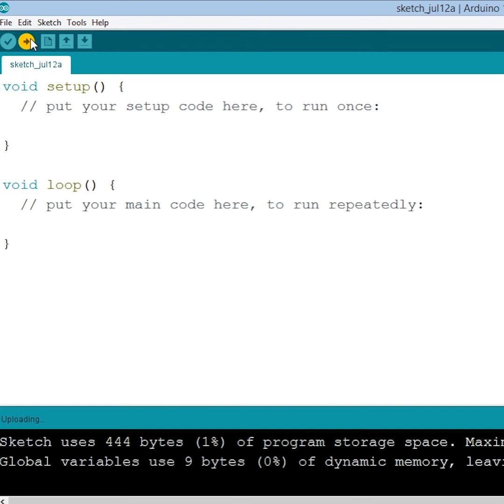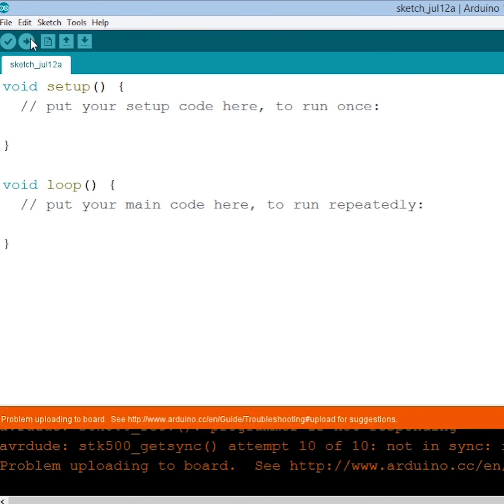As we can see right now, this error is being generated. So we should not fear anything or be bothered by it, but rather learn from it. Whenever we see this type of error, we should know that pin 0 and 1 are engaged, and we should remove the connections which are connected there. If we remove these two connections and try to re-upload our code on the board, it should work fine.